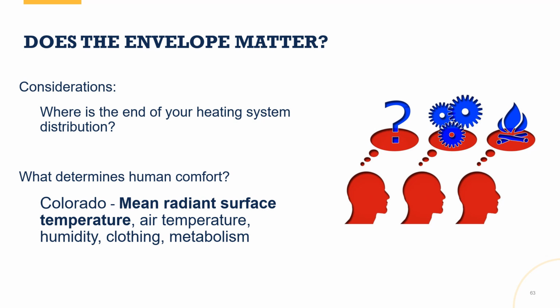So for people that prioritize comfort in their lives, guess what matters? Insulating, air sealing, windows, walls, ceilings, doors, floor. All of that is going to matter. And then let me ask you this last thing about whether envelopes matter: do smaller heat pumps cost less? We talked earlier about getting right-sized heat pumps being important for a lot of reasons, but we haven't brought this up yet. Do you think a 3-ton heat pump costs less than a 4-ton heat pump? It sure does. By how much? It depends on the brand, the model and series, and what's available at your local shop. But yes, smaller heat pumps typically cost less.